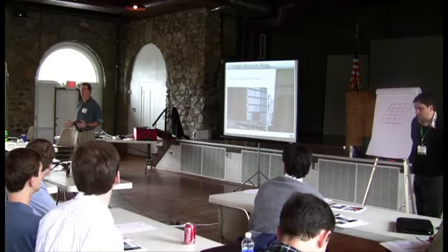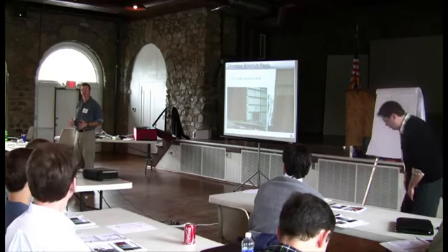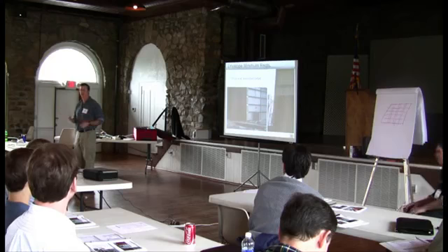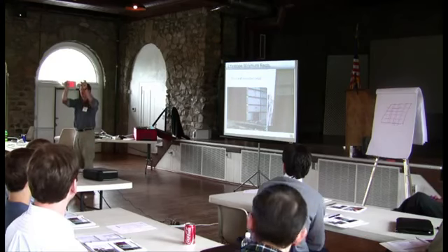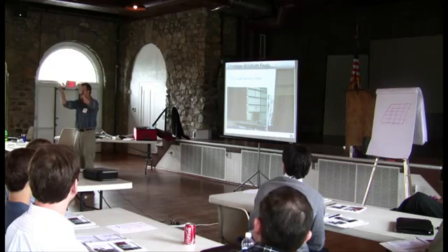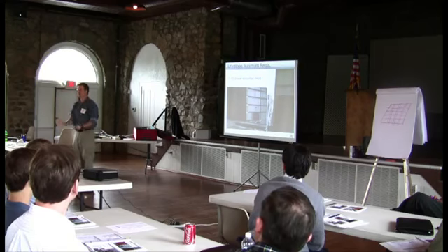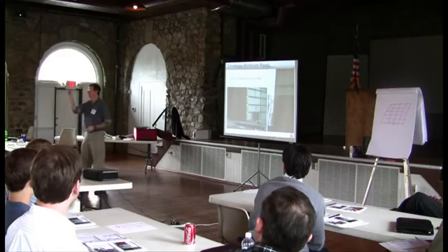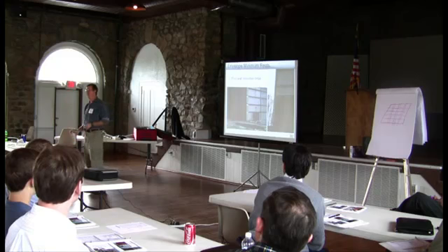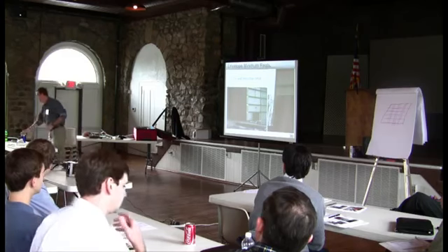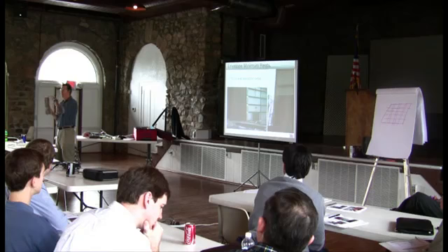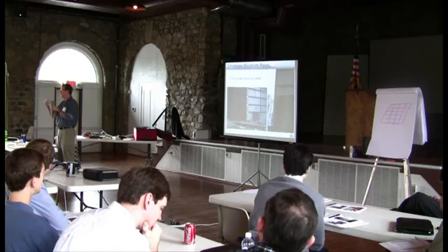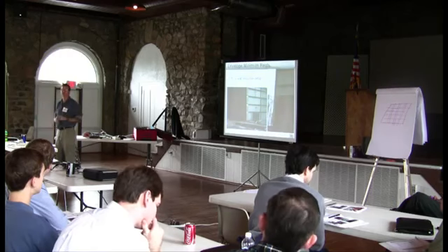Anybody ever seen zebra striping? It's when you go into a commercial building in particular, or a home, I guess, but you see spots of mold growth on a vertical thing that seem to be spaced about every 16 inches, and they're about 1.5 inches wide. And you're like, I wonder what's going on there. And it's because that's a cold surface, right? There's a very high conductivity path between the inside and the outside. And so that's what this is basically getting at.